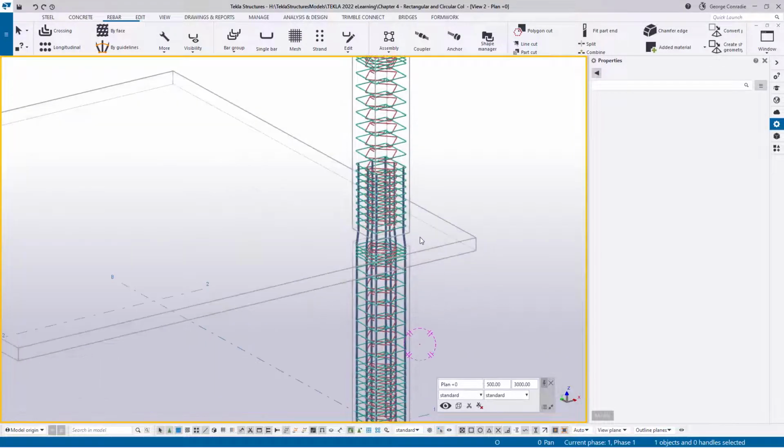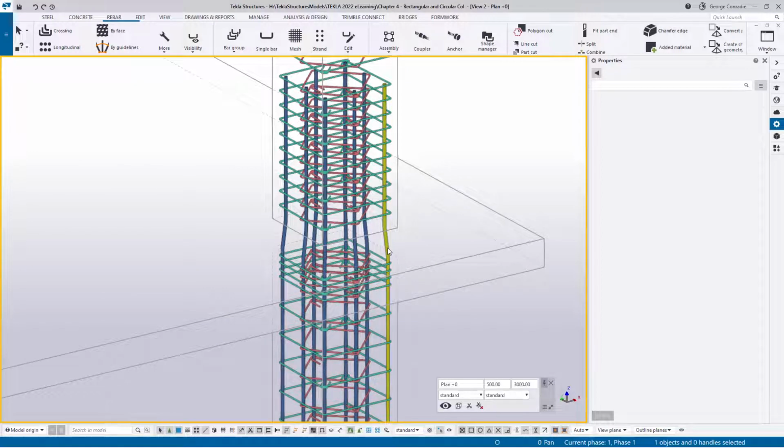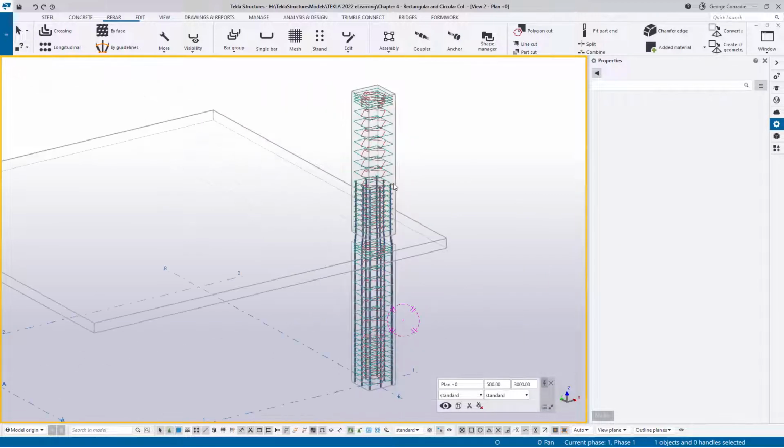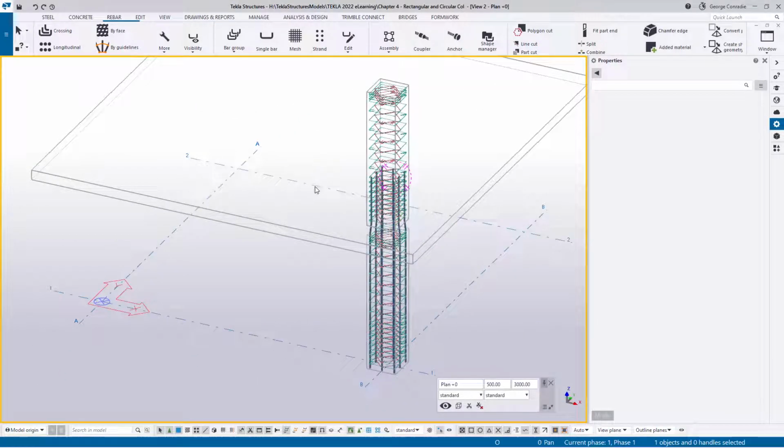And although you could change your end modifier value here, these were put in as standard single bars, so there's no end modifier here. So I'm going to use rebar sets to do these verticals quickly, and it's pretty quick.